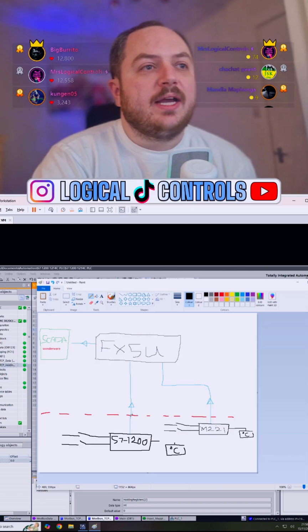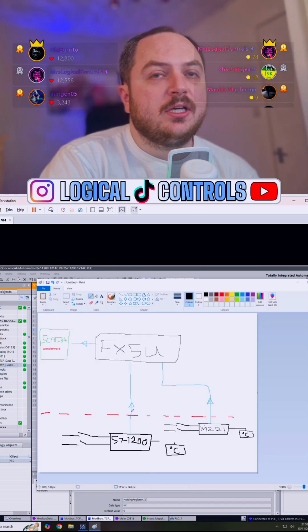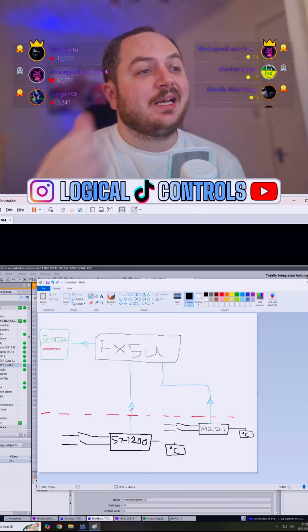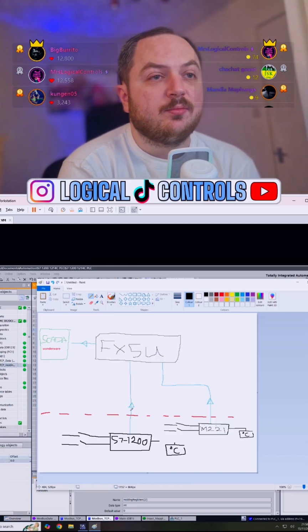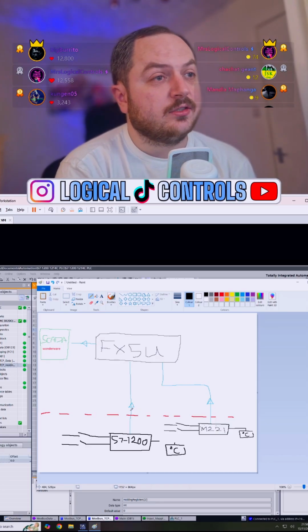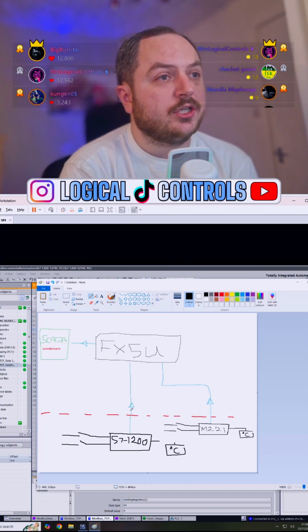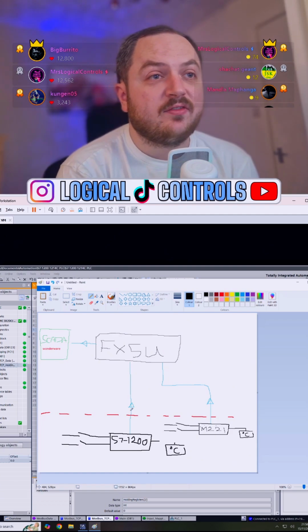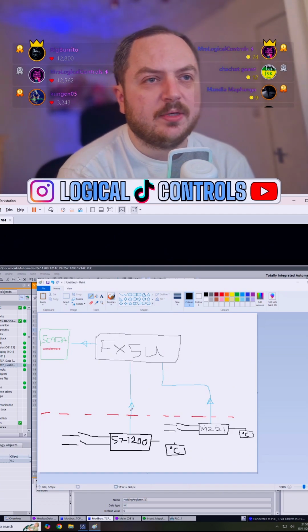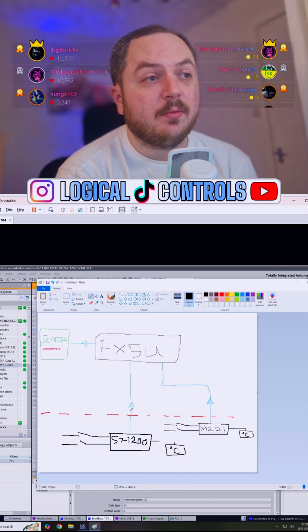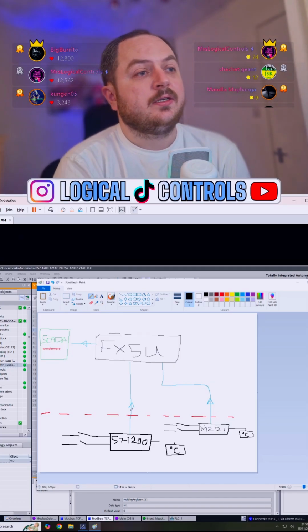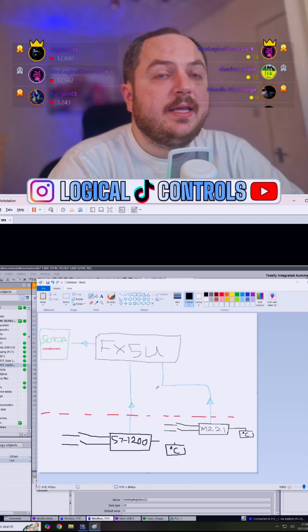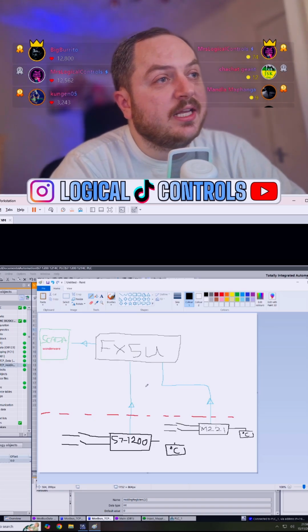And the reason so many manufacturers use Modbus, not just for its openness, but I believe it doesn't cost them anything. A lot of communication protocols have a license. If a manufacturer wants to use Profinet, they're probably going to have to pay Siemens, I'm assuming it's Siemens who made it, to put it in their controller. They have to license it. I don't believe that's the case with Modbus, and that's why it's so popular.